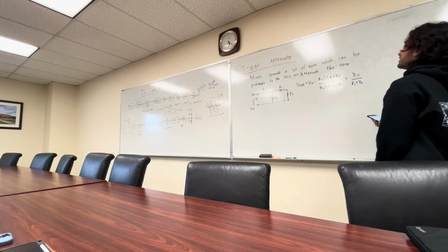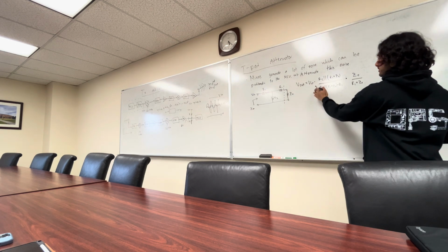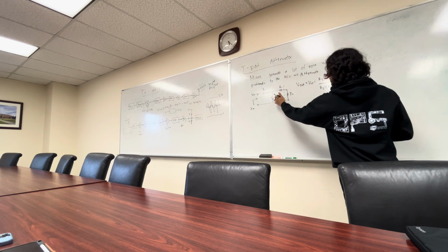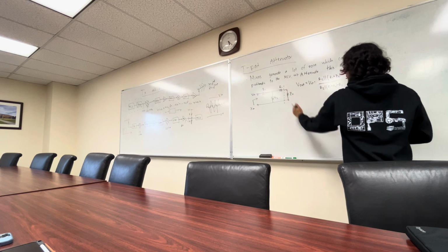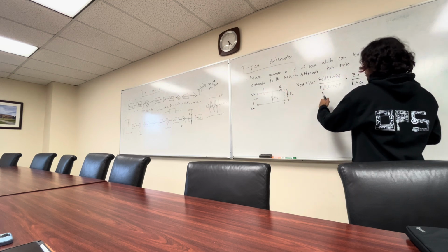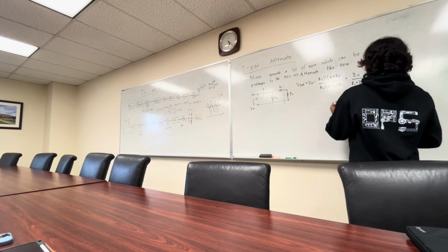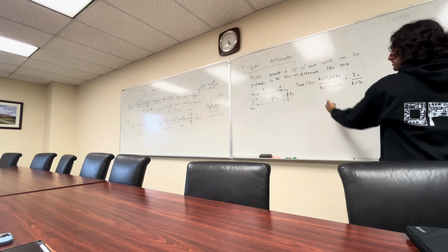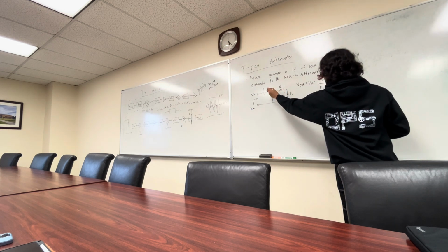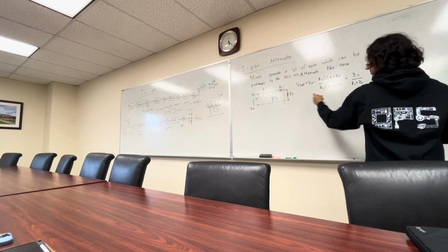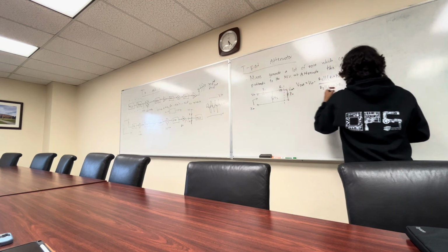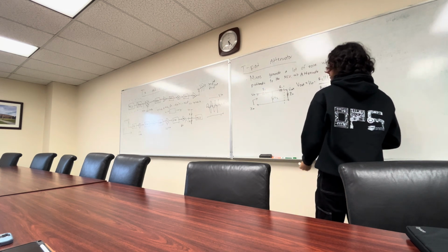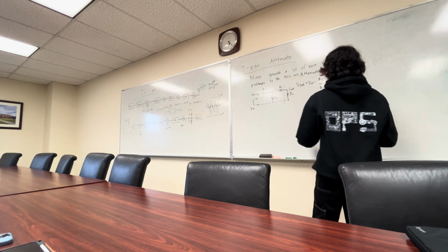So this is one equation, and you can kind of see how this develops. You have your R2 in parallel with your R1 plus Z0 this way, and then you effectively have a voltage divider between that and that R1. Then that's going to get multiplied by another voltage division ratio here to get your Vout. So this voltage here is at this node, and then Vout is going to be here, which gives you this factor there. From here, we can calculate what our gain is from Vin to Vout, which is Vout over Vin.